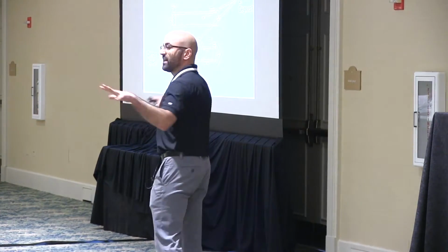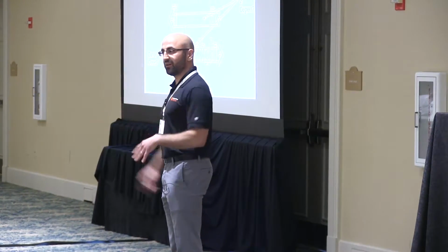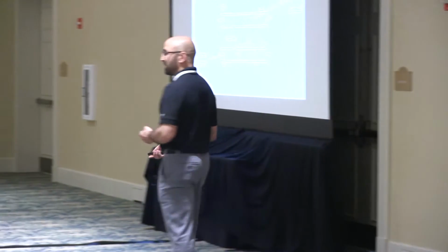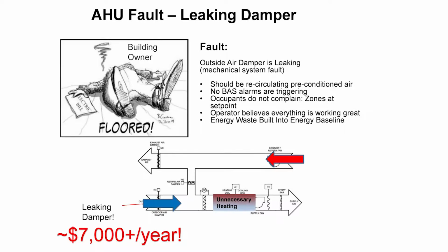And then we're deploying that across all the building systems at scale. Typically when you set up an alarm, it's for a single building system in a commercial building. The rules, if you choose the right software package, will deploy across all the building systems in a very scalable, seamless way.